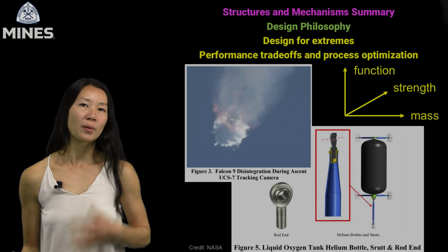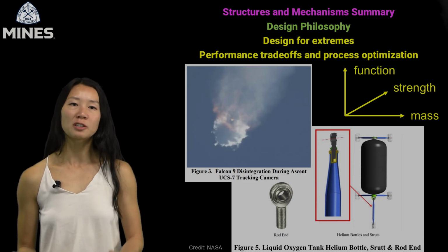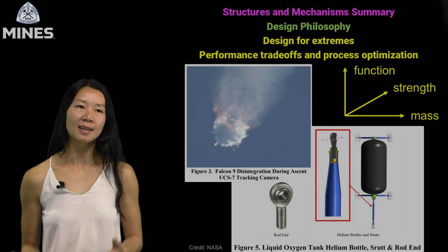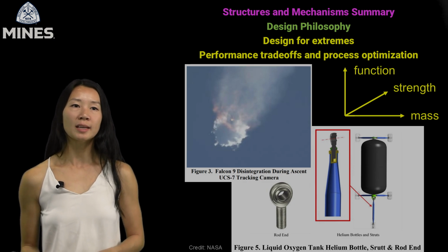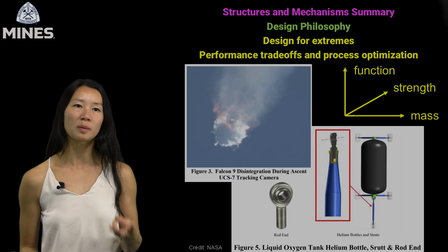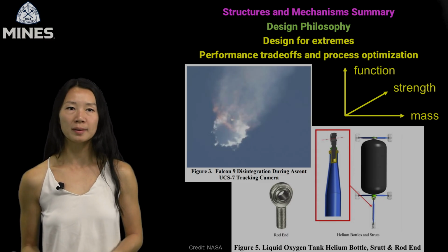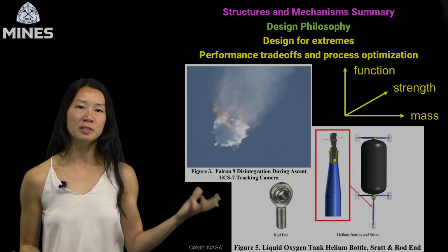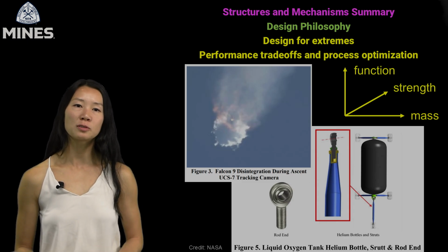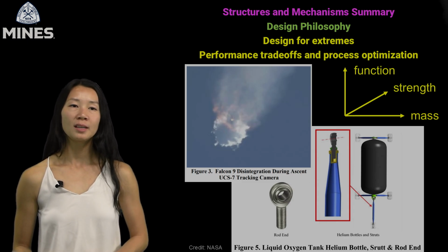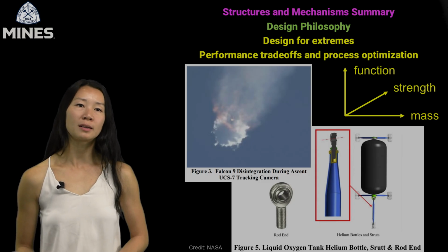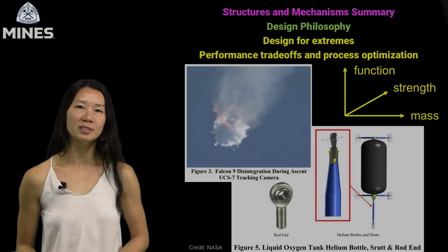The third principle I want to impart is to design with modularity, adaptability, and test access. We want systems that can be verified, maintained, or repaired, especially for high-wear components. An example comes from this story about jack screws used throughout the Kennedy Space Center. Historically, these screws relied on a single soft nut that wore down over time.